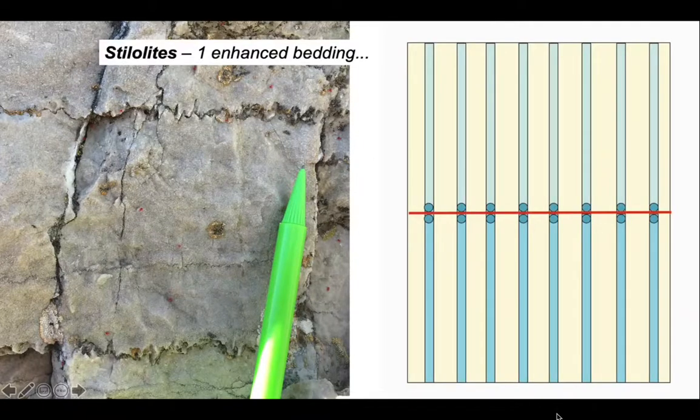Let's explore this on this diagram here, where the red line represents a bedding plane. Often bedding planes will have little bits of impurity on there which will enhance this process even more. And across the bedding plane we have pairs of grains that are asking each other which is the more soluble. So let's allow this rock to compact. In other words, we'll put more rocks on top that impose a vertical load that will ask the dissolution question across that bedding plane.